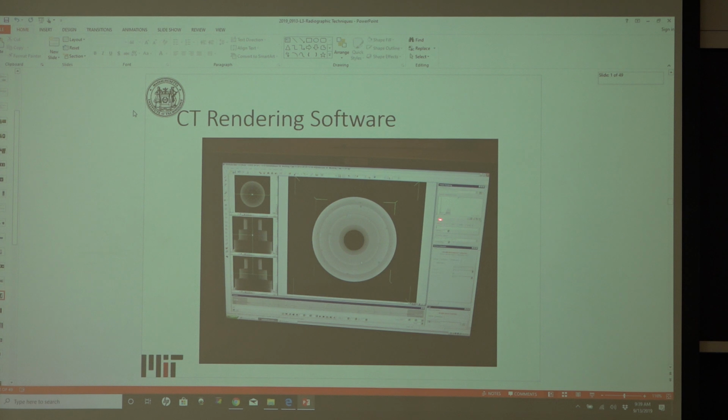The dialog box is over on the right-hand side. What's important to note here is what determines what's known as the dynamic range of the scan. This is all based on grayscale. The grayscale, I believe for this, was a 16-bit grayscale. So it's similar to if you have a 4K HD television or something like that. Rather than pixels, it's known as voxels, volume elements. And this is how you can actually adjust contrast and brightness in order to improve the resolution of the image.